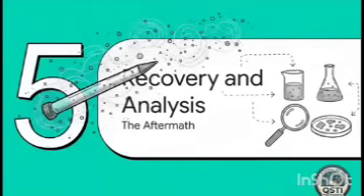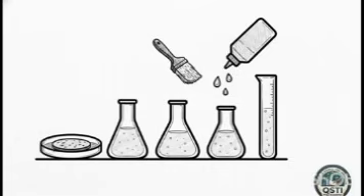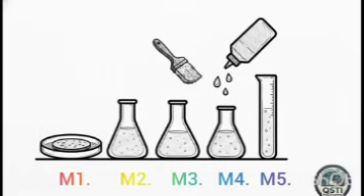Section 5. Sample Recovery and Analysis. Time for the aftermath. Recovering this sample seriously requires the precision of a surgeon. We use 5 very specific containers to cleanly segregate the particulate by size. Container 1 holds the actual filter with the PM2.5 catch. Container 2 is your acetone rinse of the nozzle and the Cyclone I catch, so that's your larger particulate stuff